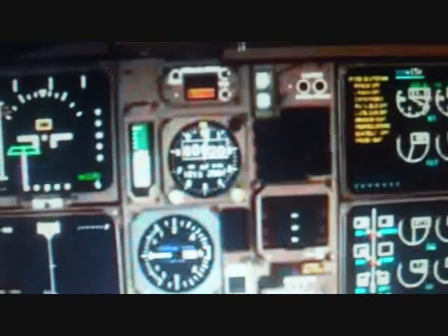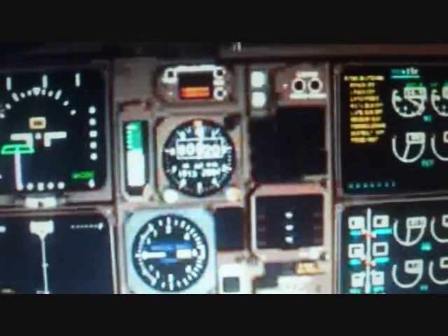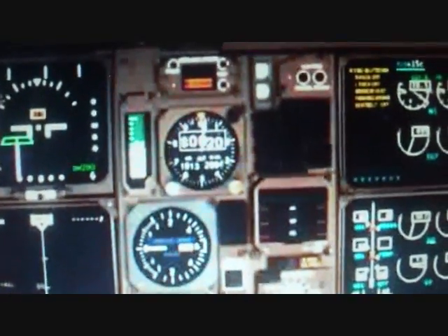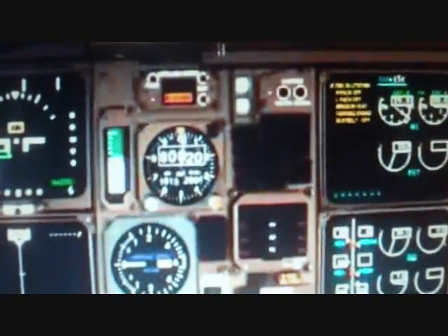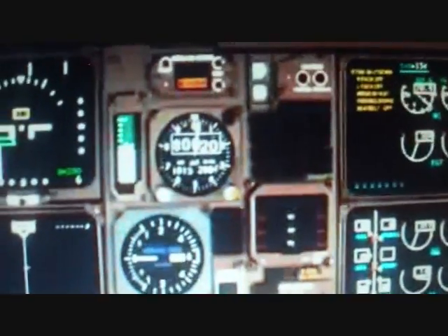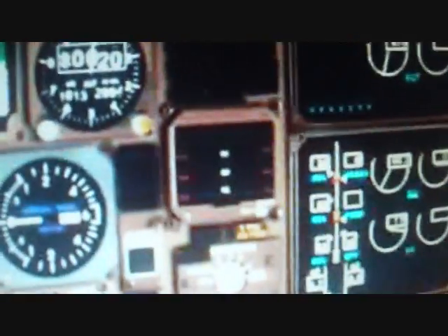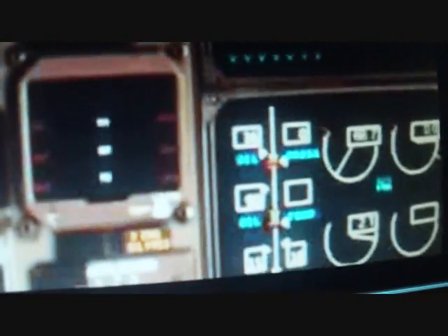And then it starts up its cycle with the starter still going, and then you're going to see it click. Now when you see it click, then power is there, you go. See that click? That click means that the power is transferred from the APU generator to the engine's generators. And when that happens, you'll see the starter switch in the auto position. That's something you must verify, otherwise the starter will still rotate and burn up.